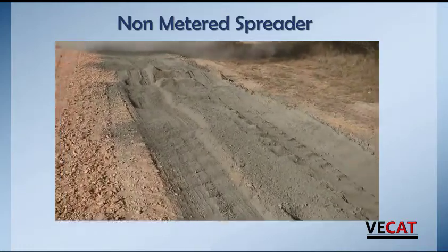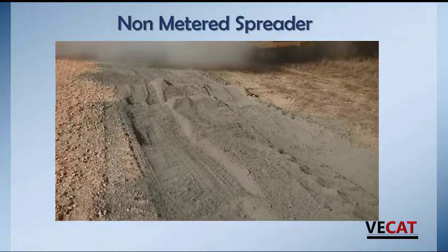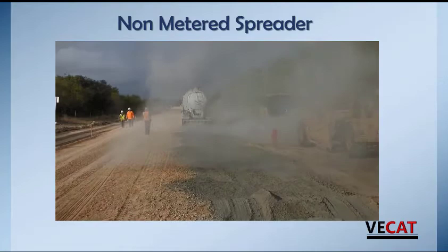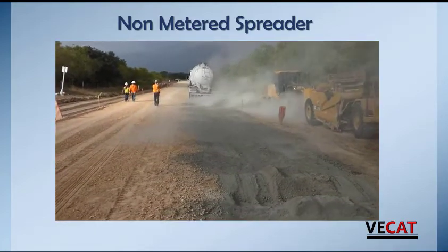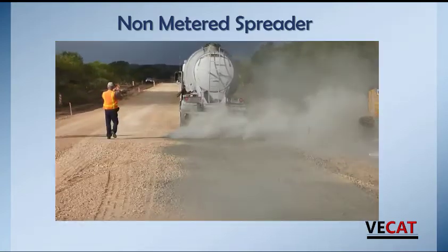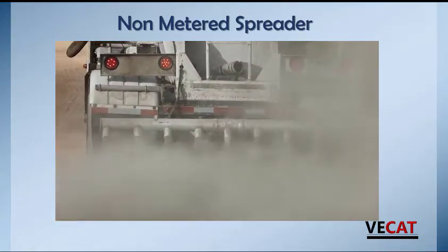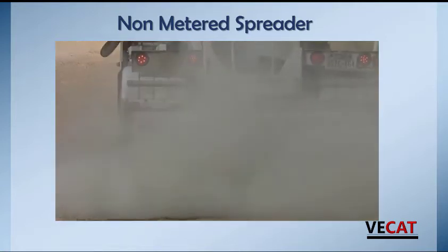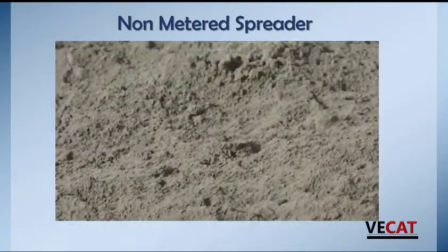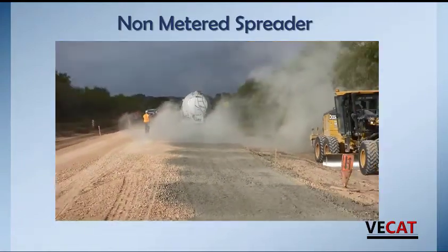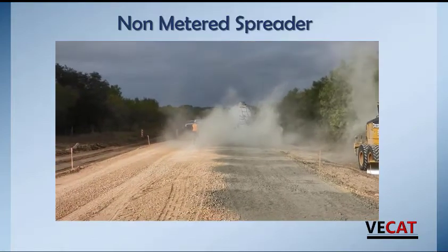What this ends up doing is making a very rigid cement, concrete-like area in those deep spots. And then in the other areas, it's very thin and not enough strength. So we end up creating basically a boulder in the road and then sand next to it. So the heavy cementitious areas end up being a very solid rock, while the rest of it is very lightweight and still underrated capacity for the road.